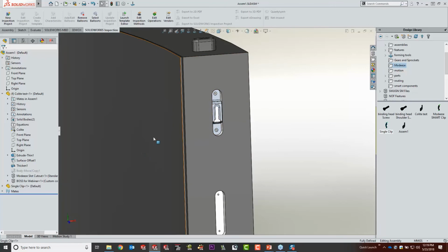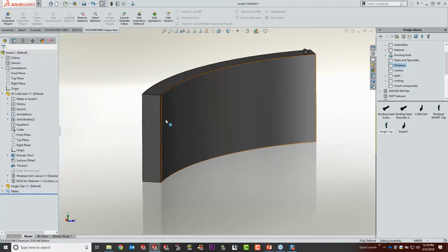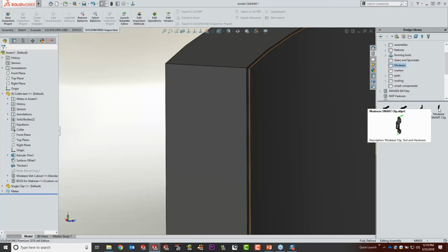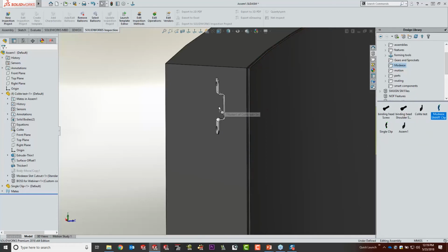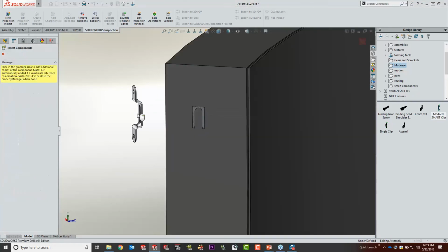Now where I ramp this up with some incredible intelligence is something called a smart component. Now in this instance, this particular piece of geometry actually uses a clip that's a smart piece. Now that clip that you just saw actually has fasteners that hold it in place. It of course had a slot that I placed it in, and then it also has other parts it needs to mate to. Well, you can make clips that actually do that, not part of this demonstration, just want to show you the results. But it's a complete self-contained clip that as I drop it into place, I can go ahead and position it, which there are no places to mate to, as you can see.